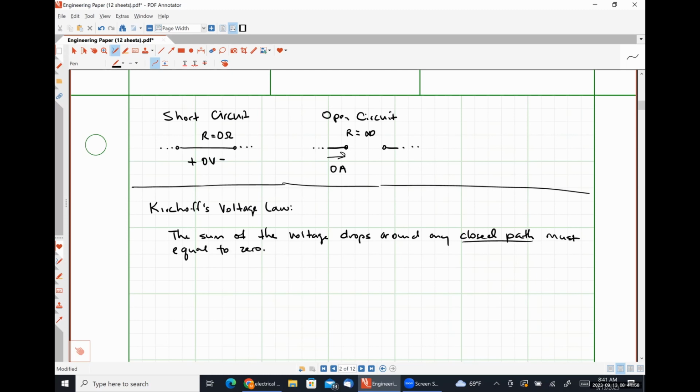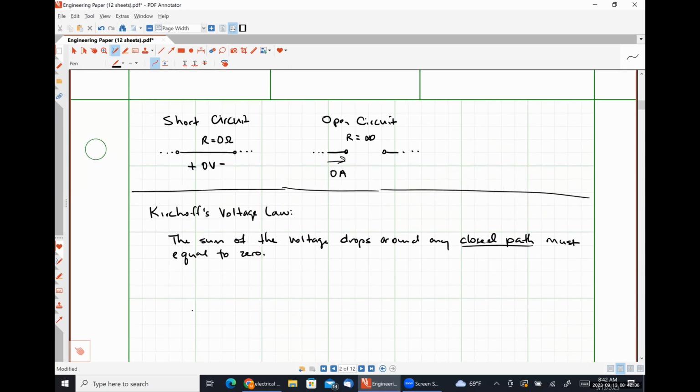All right. So before we work some examples here, why does the sum of the voltage drops around a closed path have to equal 0? Might be an odd question. Remember what we talked about in Monday's class with respect to voltages. Anytime we have a voltage, we're looking at a transfer of energy. Well, if we start our path at one point and end at the same point, we are in a conservative system. So effectively, we're saying the potential difference between this point and the exact same point has to add together to 0.